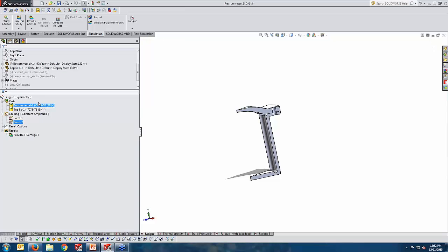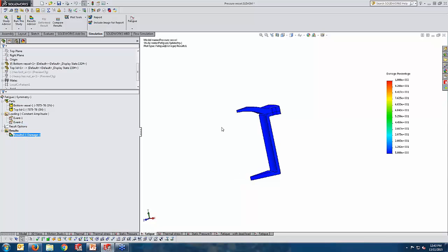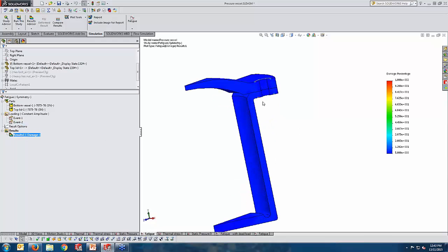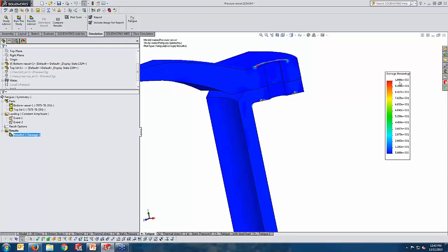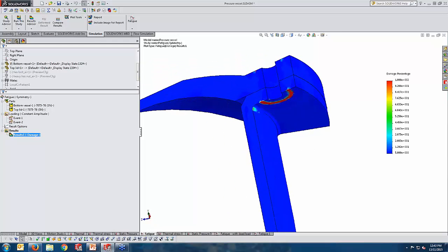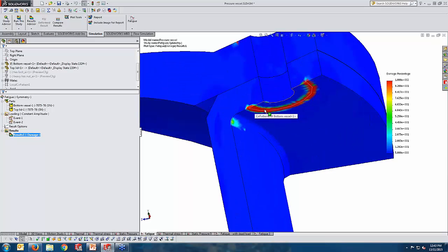With those events and correct values of SN curves, I can look at the result of the damage. You can see there are some places where we have 100% damage, and we can definitely comment that since the stresses are singular there, those values are not what we are considering, and we can simply ignore them. That is because of the bolt connection and the axial forces we have there.